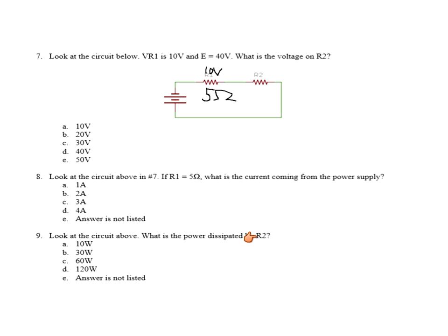A little tricky there. If I take 2 amps times my source voltage, 40 volts, I'm going to get the total power. But are they asking for the total power? No, they're asking for the power in R2. So focus in on that particular component. Focus in on R2.